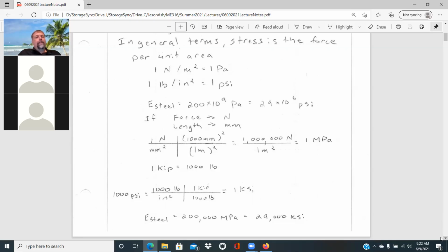The other thing is we'll be doing this as we go through example problems, just to show a nice unit system to use and going from there. Another thing that will show up is a force in kilonewtons and a length in millimeters. If you're in kilonewtons and millimeters, the Young's modulus and stress would be coming out as gigapascals, and you'd only have to use 200 gigapascals in your calculations.